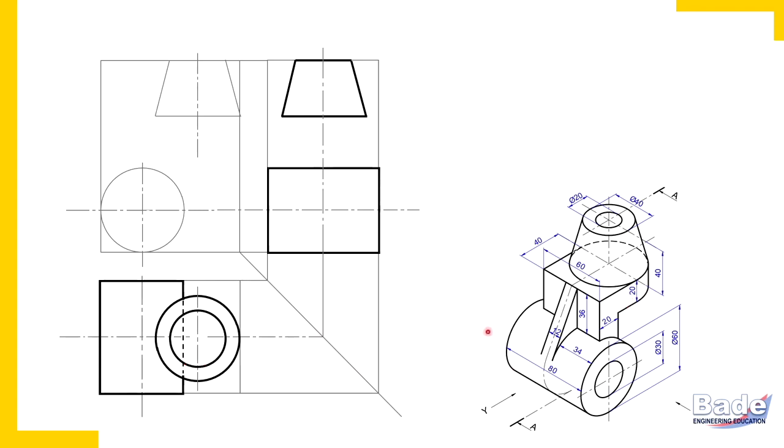So let's complete that U shape. Principal edge. Curved edge is already available here. Because curved edge of that U shape surface, this curved edge is coinciding with the curved edge of the base of truncated cone, which we have already drawn here. Now we should draw these three principal edges parallel to width and these two edges parallel to length. So watch here, I am drawing.